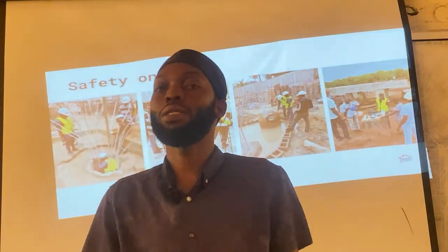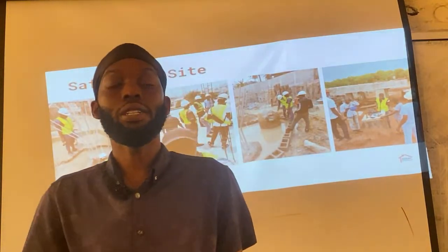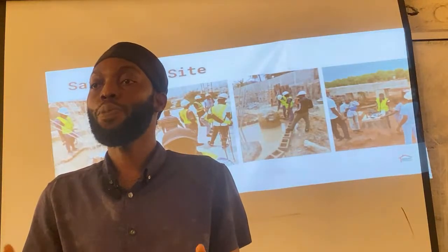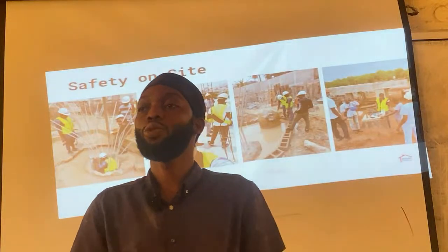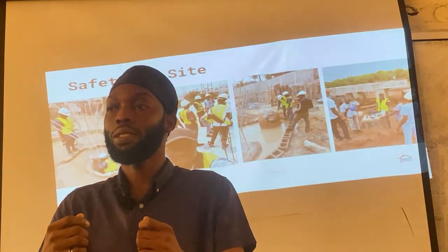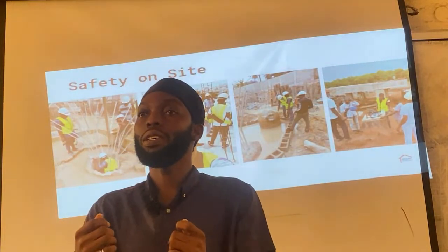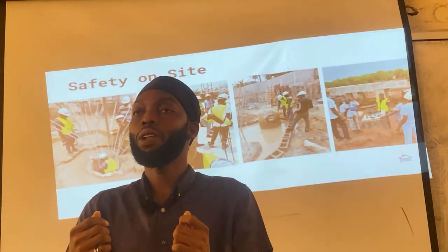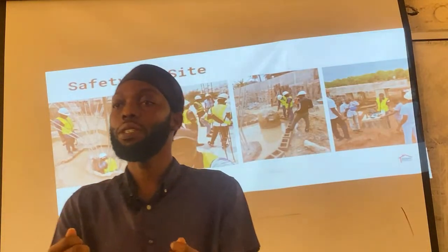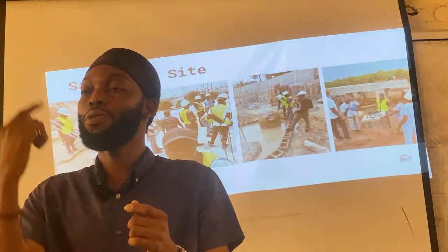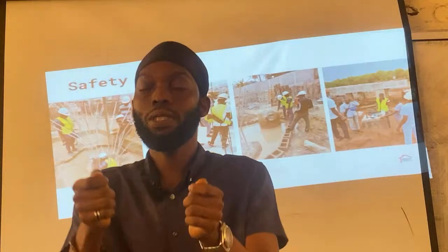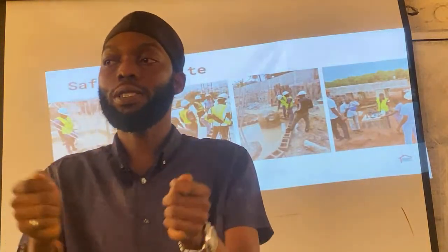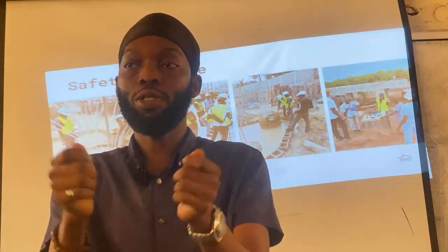We have smooth surfaces. I mentioned something earlier, the couplant. So we rub it on the surface of the transducers. That will create a void-free interface between the surface of the concrete element and the transducer. So when you put it there, there will be no voids. That couplant will fill all the voids there.